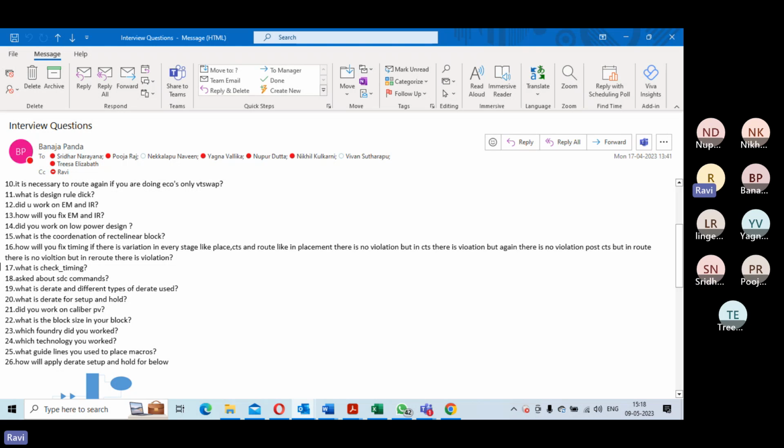Now, if you have to strengthen the net, how will you strengthen? We can use the double width. You can move to the higher metal layers. Shielding? No, shielding, how will it help? Shielding won't help. There's no crosstalk. This is about the current carrying of that net. Shielding, how will it reduce the current carrying?